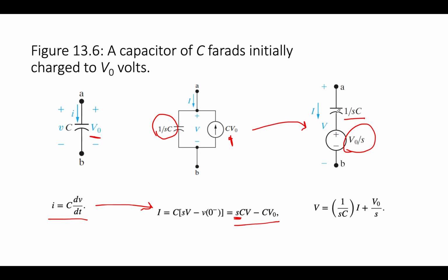So inductors and capacitors in the Laplace domain both become functions of S. And when we do the substitution of the element, we're basically taking this circuit shown here and we're substituting it for the time domain circuit, so that we're going to be able to write node and mesh equations, voltage divider equations, whatever, directly from the Laplace domain equivalent circuit instead of taking a time domain circuit and trying to do a differential equation.